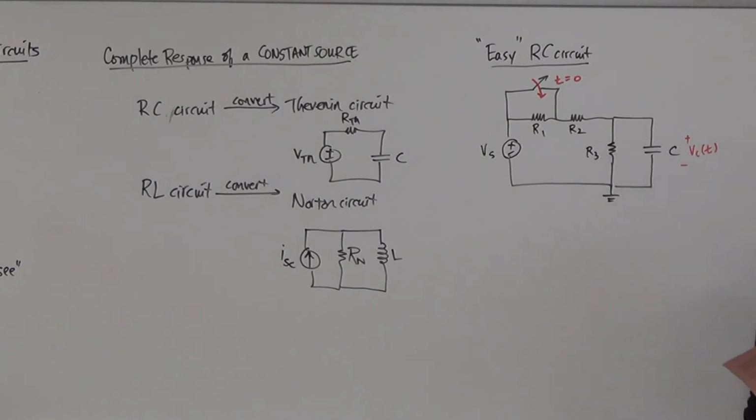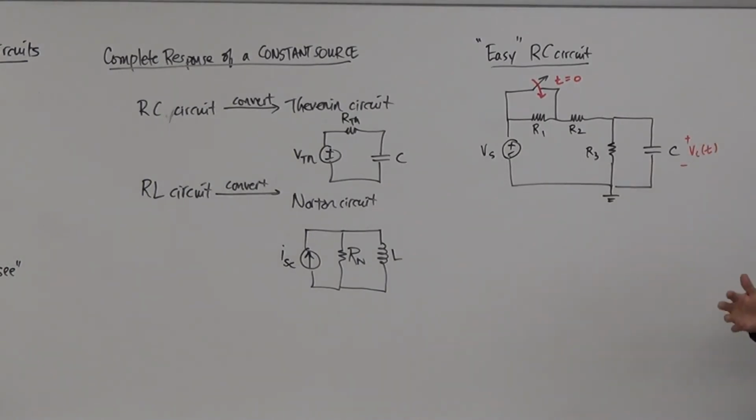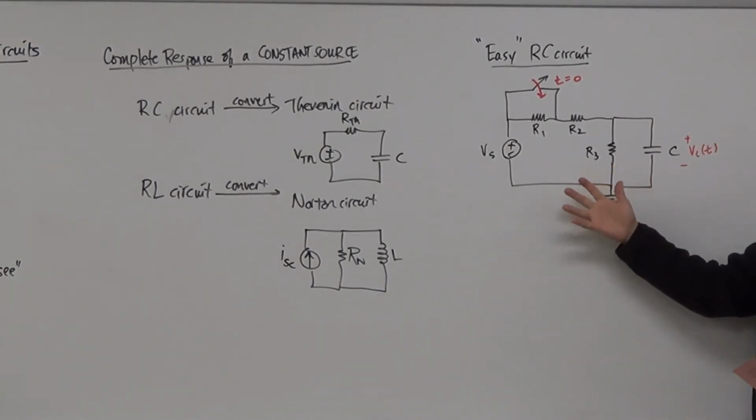Why does it require a first-order differential equation? Because the capacitor is not a linear element. It depends on time. So if I integrate the capacitor equation, or write the capacitor equation in this language, you'll see that I'll be able to either derive a differential equation or have an integral equation. And as a consequence, you end up with an initial condition.